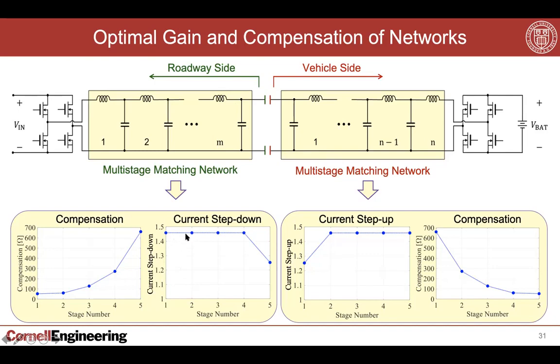As far as the voltage or current gain is concerned, you try and provide as much of that early so that you get up to high voltages quickly, and then whatever difference is left, you provide that from the last stage. So essentially, you try and max out the gain from the early stages, or the stages further away from the coupler.